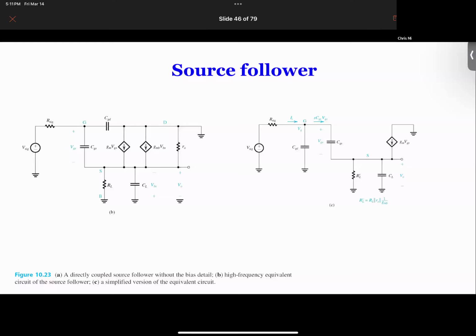The VGD is to, so you see, this is ground, right? That's why they can move VGD to ground. So we move VGD to ground. However, one thing you have to be careful about: CGD and CGS are not in parallel, because these things connect over here. That's critically important. And this is another mistake our students often make: they simply put CGD and CGS in parallel, and they think they got everything beautifully simple by adding these two, but that's not correct.